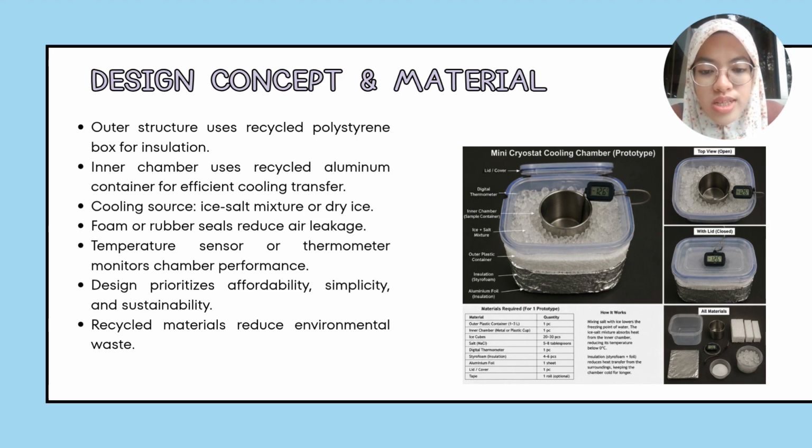The cooling source is an ice-salt mixture. Normally, ice melts at 0 Celsius, but when salt is added, it lowers the freezing point of water through freezing point depression. So as the ice melts, it absorbs latent heat of fusion from the surrounding, which causes the temperature of the mixture to drop below 0 Celsius, which depends on the salt concentration.